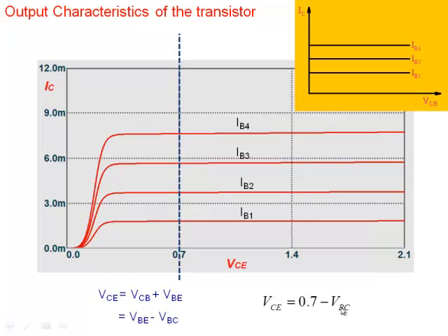But all of you know that forward bias of a junction really means what? I have to apply maybe 0.5, 0.6 volt, then only it gets really forward bias. The effects of forward bias you begin to see. So ideally, collector base junction starts getting forward bias right from here. But until you make the collector base junction forward bias by a certain amount, you won't see its effect. So we'll come to that.